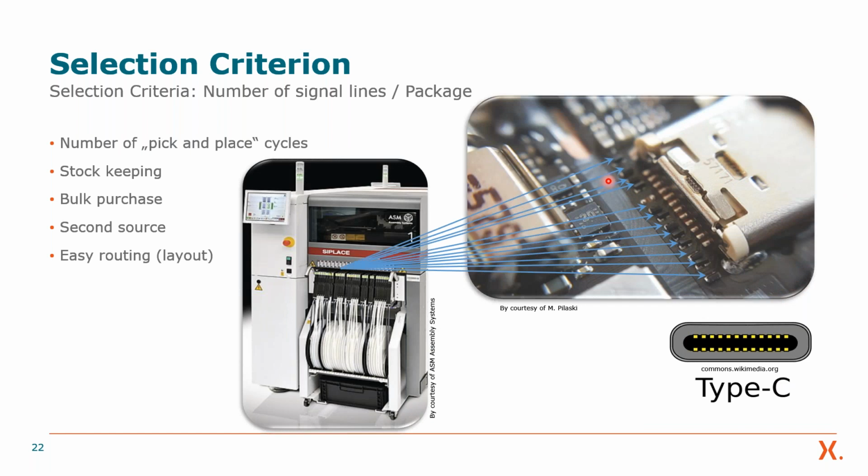This is a USB connector of a cell phone. And you see these tiny devices. These are all ESD protection devices, and you can see that you can place them closer to the connector, which gives you a higher robustness, as Lucas already explained, and it gives you a bit more freedom when it comes to routing, because otherwise you always have to route your traces to the ESD protection device. If you have a single device, you can put it where you want.